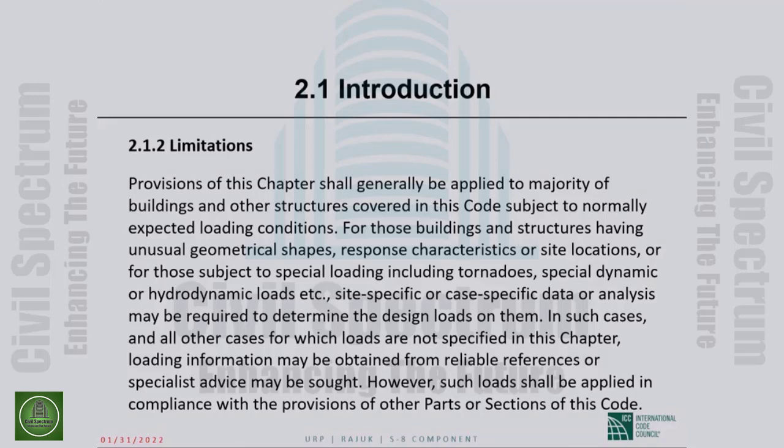For those buildings and structures having unusual geometric shapes, response characteristics, or site locations, so unusual geometric shape, unusual response characteristics, or site locations, or for those subject to special loading, including tornadoes, special dynamic or hydrodynamic loads, etc., site-specific or case-specific data or analysis may be required to determine the design loads on them.